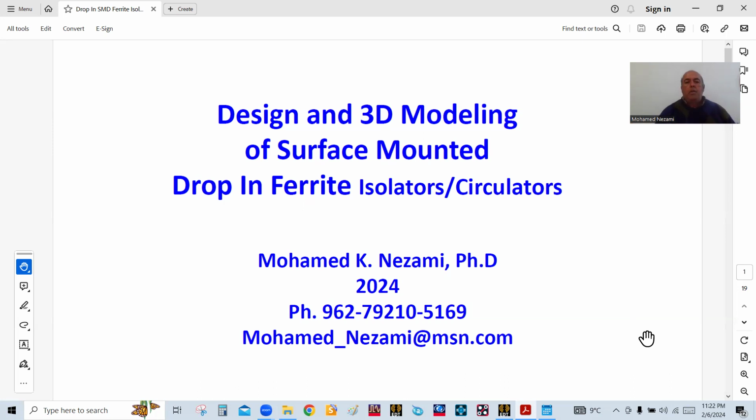Last session, I covered the overview of the principle of ferrite isolators and circulators and their application. And I introduced two different designs that I will be presenting. Both designs are designed theoretically first and then are implemented into the 3D modeling tool from ANSYS HFSS.